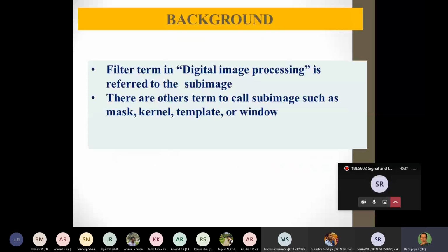Because for a spatial filter, one of the things that is necessary is, one is definitely the image, or what you consider as the signal in signal processing is going to be replaced by an image. In addition to an image, we had just seen in our problems just before when we had discussed 2D convolution that we had a filter, and I mentioned that that filter is termed by different names like mask, kernel, template or window.